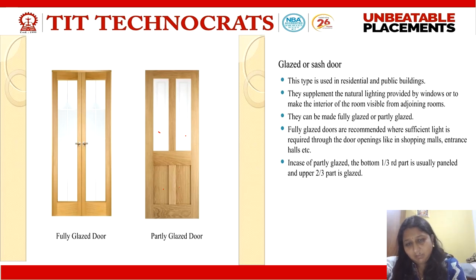Stile is the vertical member. Panels are that portion created. Panels are created with the help of rails. Top rail, bottom rail, lock rail, and if it is an 8-panel door, we may have a freeze rail also. This member is called as what? Muntin. Now, our next type of door is a glazed or sash door.